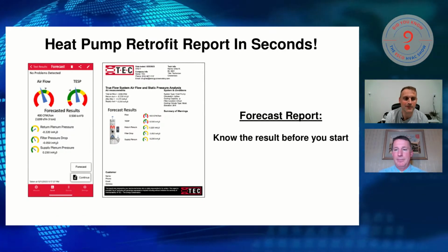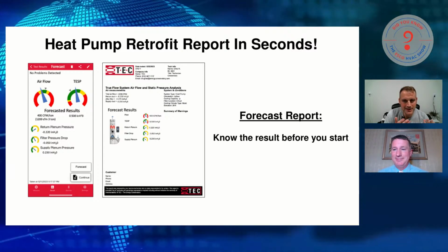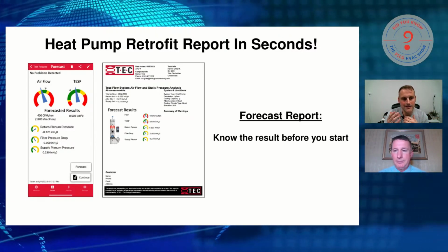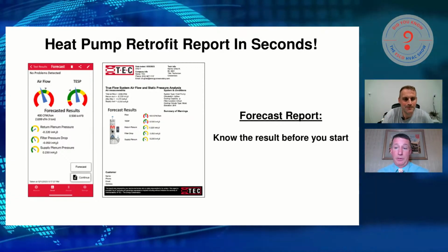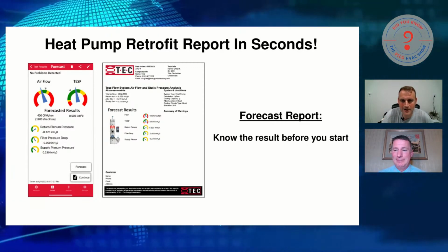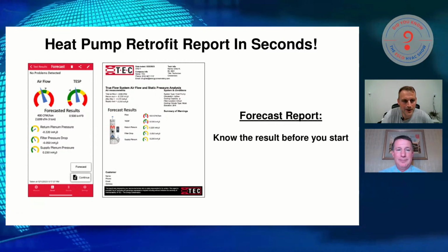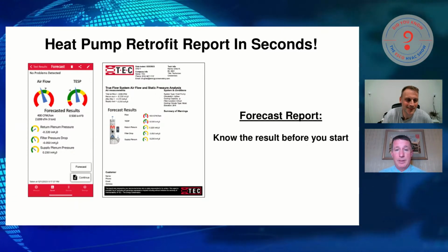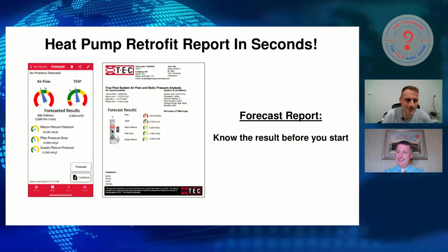You'll have 2 reports. Yeah, right? Exactly. Because you essentially have 2 systems at that point. You have heat pump heat and you have furnace heat, with separate airflows. And your heat pump's going to move a lot more air than your furnace. So that's the one I would be most concerned with external static pressure. Yeah, that's how I would handle that.